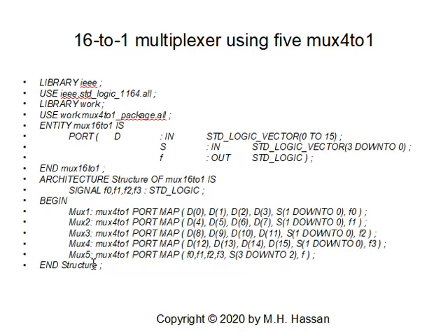This uses the 4:1 multiplexer and utilizes the package, and this is called hierarchical code because this is a higher hierarchy than the MUX41. We can use the 16:1 if we package this. We can package this and use it in another program. Don't forget, if you do packaging, you must always link it with the use work library, and you have to define the package here.